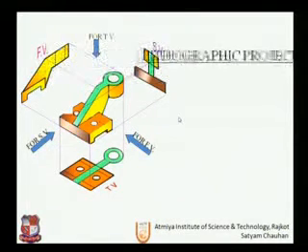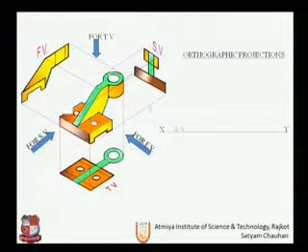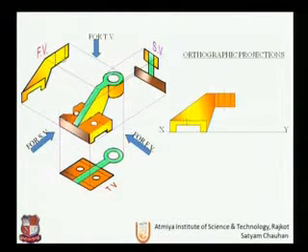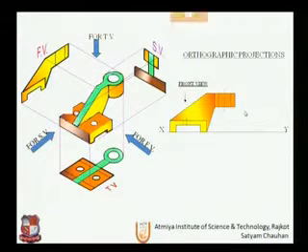Let us see the orthographic views for this. First draw the XY line and copy the front view. So here is a circular part. Since it is a drilled object, the hollow section here is represented by the center line, the long chain thin line, and observe the difference between the chain line and the hidden line here. So hence it's the front view.